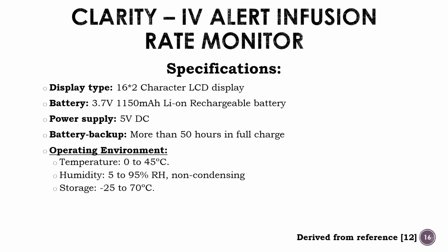It displays the approximate rate of infusion, the total time and estimated time of infusion, and sounds an alarm on reaching the target volume. Low power electronics, it sounds an alarm on zero flow detection, and is lightweight and easy to use, with one step installation, easy to mount on any kind of stand. LED indicators for low battery, alarm and charging, and a rechargeable lithium ion battery for backup for more than 50 hours of continuous operation.